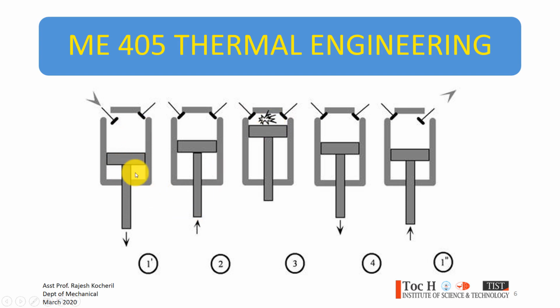Now after this suction process, as the piston moves up, you can see both the inlet and exhaust valves are closed, so the charge is being compressed. When the piston exerts work on this fluid, the temperature and pressure increase. And then when it is about to reach the TDC, the spark is initiated and the charge inside ignites in a propagatory way, maybe something similar to waves.